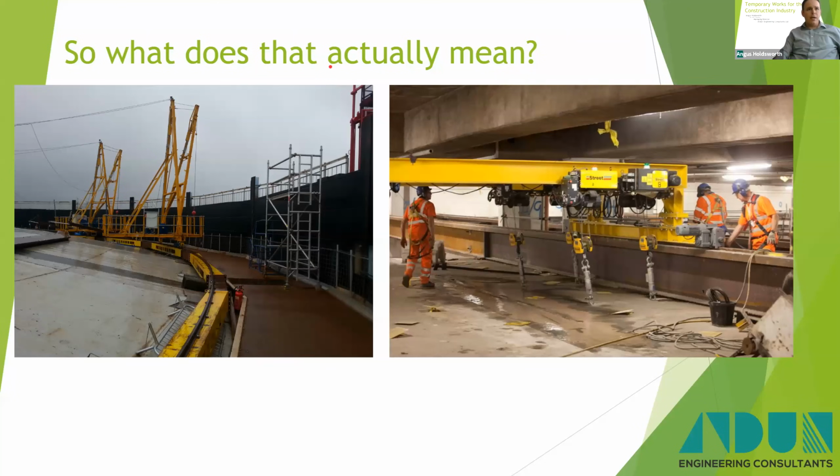And the way we do it is we pump the piston up to the roof level, cut the roof free, and we build these working platforms and crane systems on top of the piston and on top of the floating working platform. That floats on a bed of air and allows us to sequentially deconstruct the structures from the top to the bottom. Again, it's quite an interesting project, and one that we'd like to do a case study on in coming weeks if people are interested.